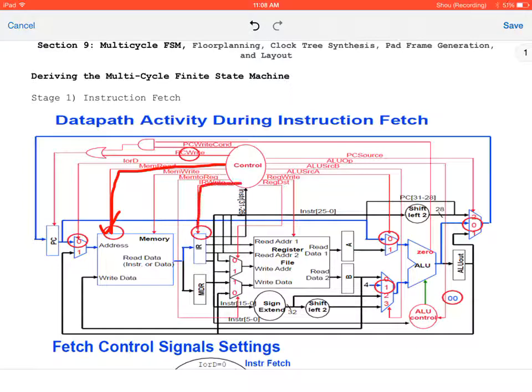IR write is going to be 1 because we're actually going to be physically updating the instruction register, because we want this to indicate it's an instruction. Otherwise, it's going to be 0, meaning we're not going to update it. This is important because every clock cycle, if you remember from the previous lecture where I had the clocks indicated, the way the register works is it holds the value until the next clock cycle, and then it propagates that value onto the data path. We do not want this to physically propagate an instruction if it's not an actual instruction. So if we're getting some sort of data from the memory, like we're using the memory data register, we want this IR write to be 0, so that only the most recent copy of the instruction is propagated.